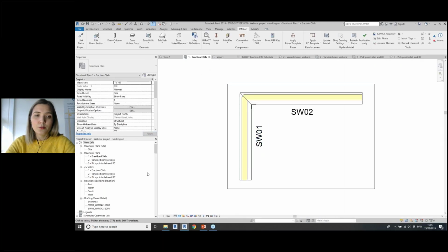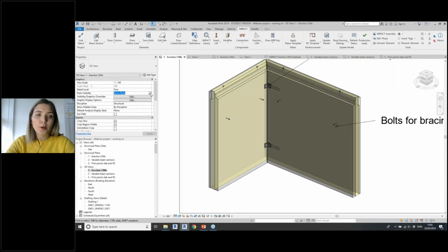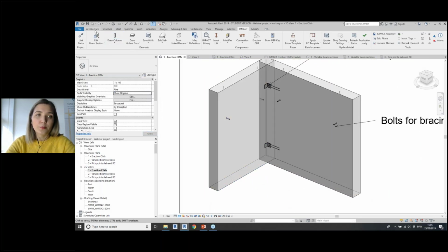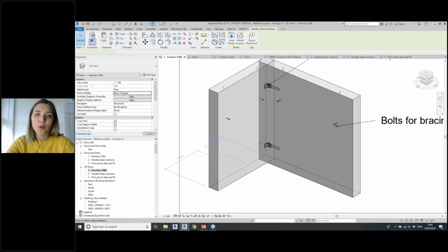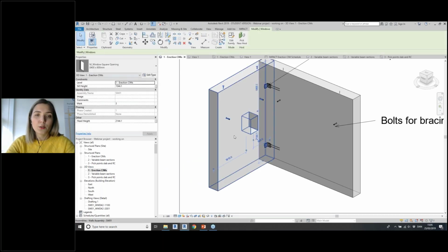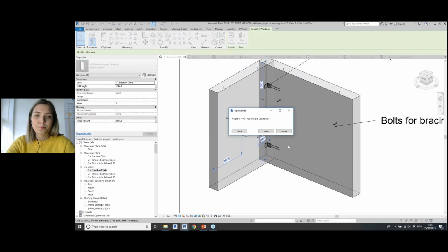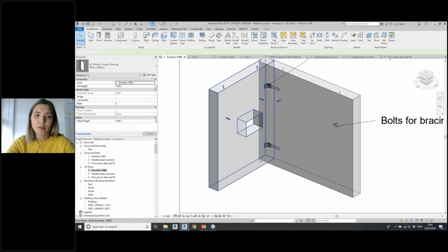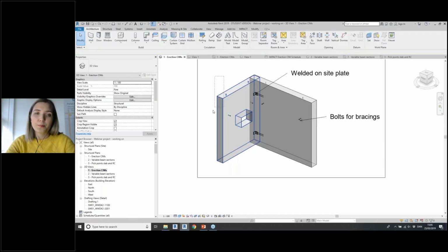And let's try to go to the wall that we made recently. We draw a window using show original, and using the architecture tab, we pick the window that we want to have in our element. I will probably make it bigger, so I select the family and I change the type. So I need to save my element again because it was recently changed, so it should come with a star by the element mark.